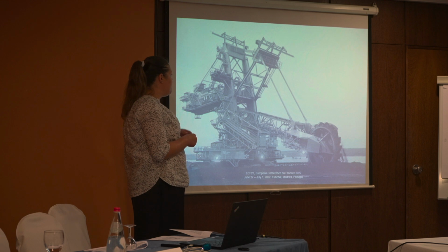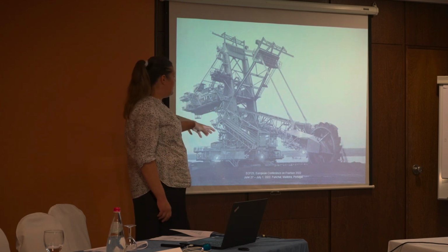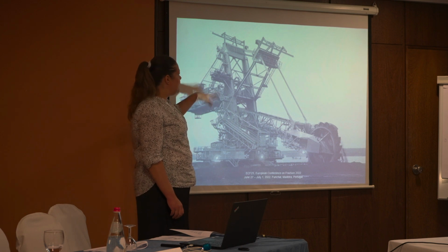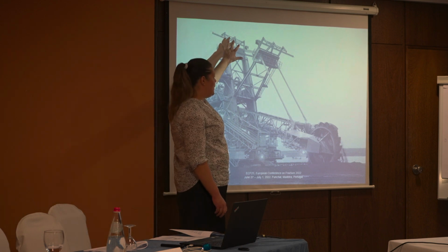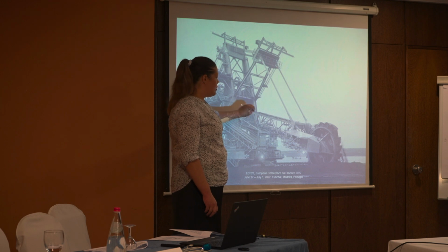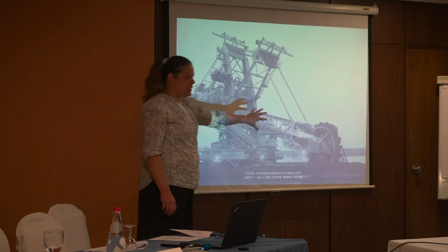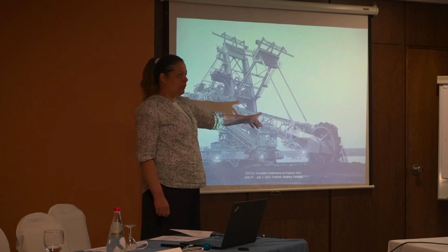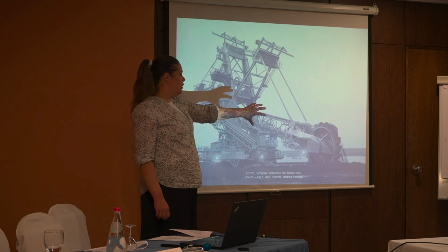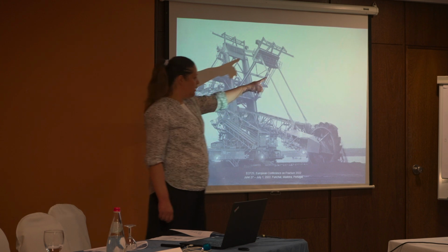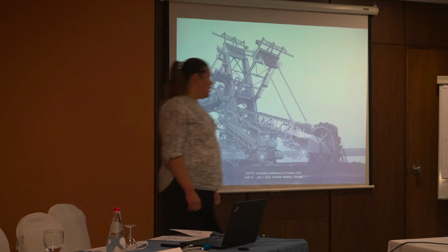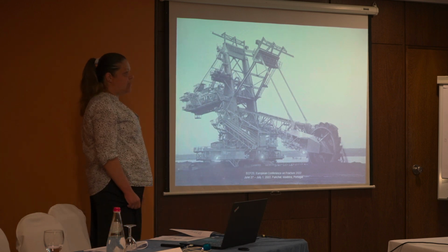I forgot to tell you in the beginning that this stress was obtained for a loading case that included the weight of this construction, the weight of all of these parts, and also included workload. Workload means overall digging force, including vertical, lateral, and the other digging forces as well.